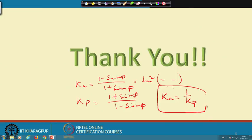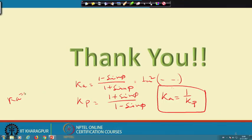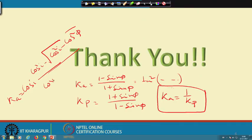From there we can see that Ka equals 1 by Kp. This is another point to be remembered. When there is a sloping surface, then Ka is modified: Ka equals cos i times (cos i minus under root of cos square i minus cos square phi) divided by (cos i plus under root of cos square i minus cos square phi). The corresponding Kp will have minus and plus interchanged.